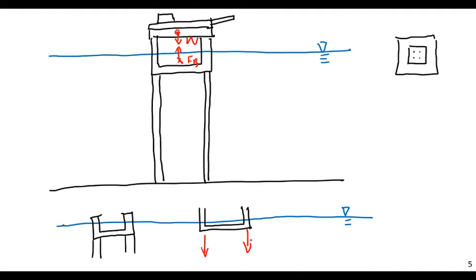So you have this immense tension force that will then be holding the platform in place. And these tendons can be quite long. They can be hundreds and hundreds of feet long, sometimes up to 2,000 feet of water. And there are other tension-like platforms I think are good to about 1,000, 2,000 feet of water. Beyond that, you need to use other platform designs, or even do just subsea drilling.